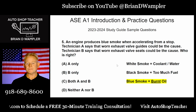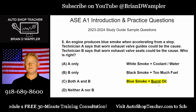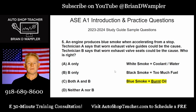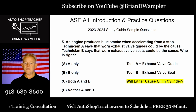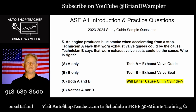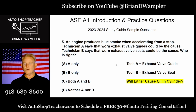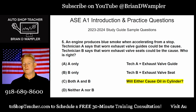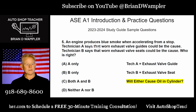Here's your reminder. What kind of smoke are we talking about? Blue smoke, so typically an indication of burnt oil, oil that's been through combustion. Tech A, again, is talking about the guide. B is talking about the seat. And my question to you, as you're choosing your answer for this one, will either of these cause oil in the cylinder? The exhaust valve guide and the exhaust valve seat. And remember, my question comes with the same conditions as the question here.